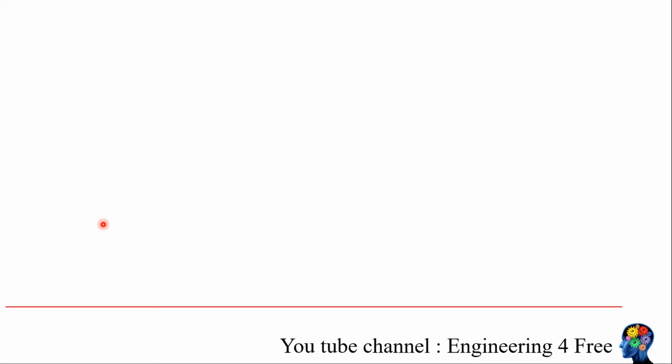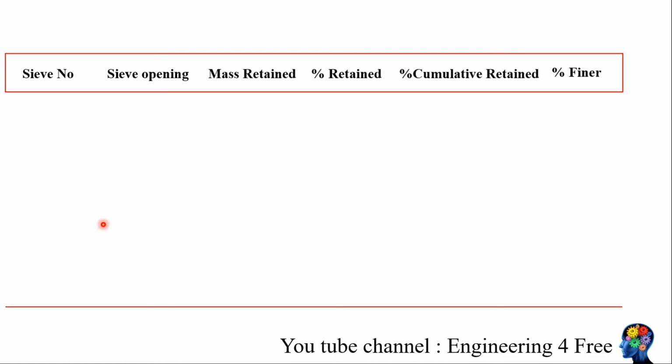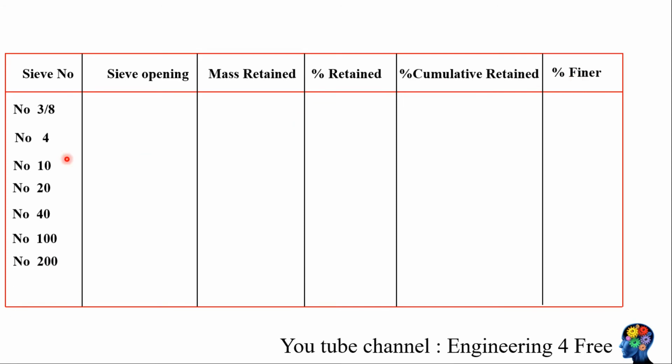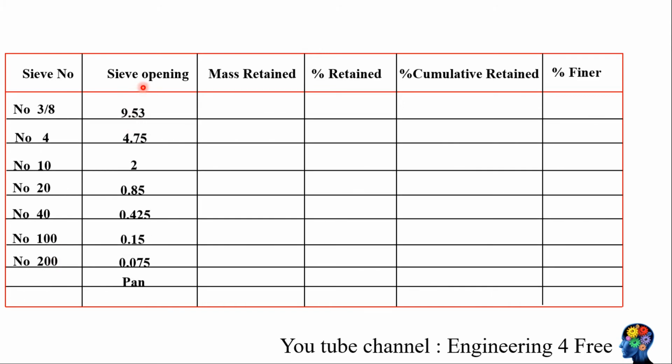The first thing is you have to construct a table. You have sieve number, sieve opening, mass retained, percentage retained, percentage cumulative retained, and finally percentage finer. We have sieves from 3/8 up to 200. You have sieve openings in millimeter corresponding to each sieve size. Remember that the pan is not a sieve. The mass retained is given for each sieve.